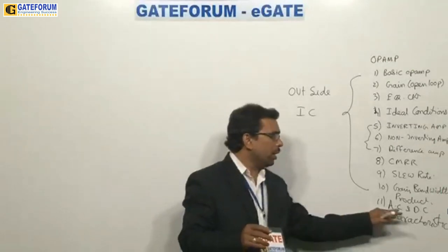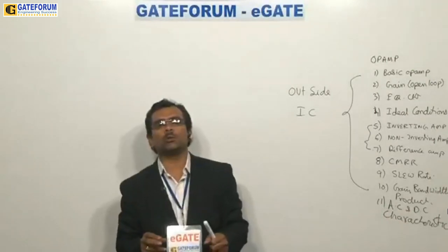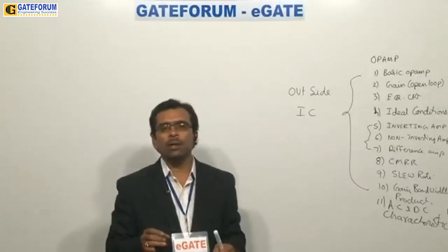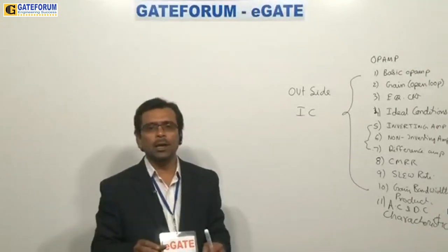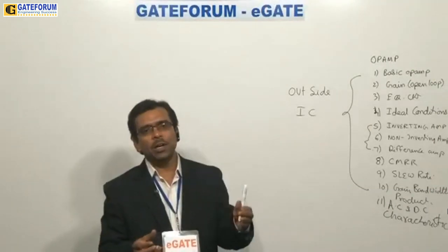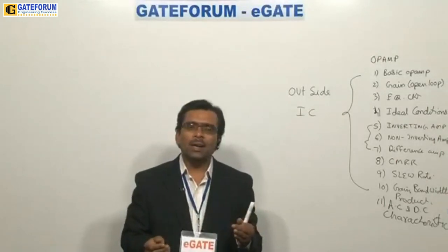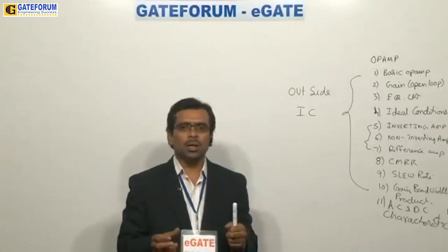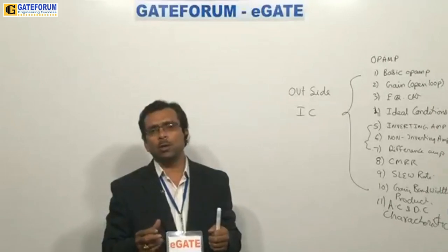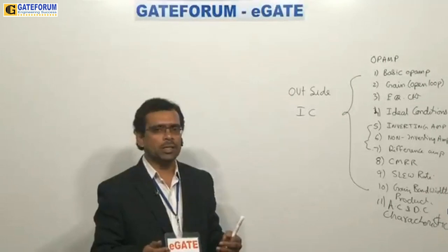That is the reason we study the DC characteristics as offset values. What do you mean by offset values? When the manufacturer has provided biasing properly, there is nothing for us to do. The moment we give an AC input, definitely you are going to get an amplified output at the output terminal. But practically you will find some errors, which we call offset errors. Offset error means when I don't give input, still I get some output, due to various reasons which we have discussed earlier.